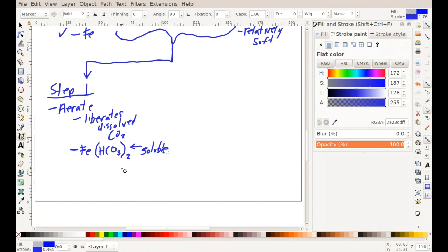And so here's what happens with this iron bicarbonate. If that gets through to any ion exchange resins, so if we've got sodium zeolite softeners, if we've got demineralizers, if we've got dealkalizers, anything that has an ion exchange resin, the iron will foul the beads, or just say wreck the beads. So it wrecks ion exchange resin. So we don't want that.